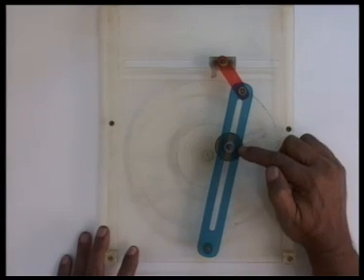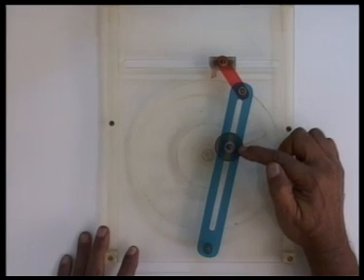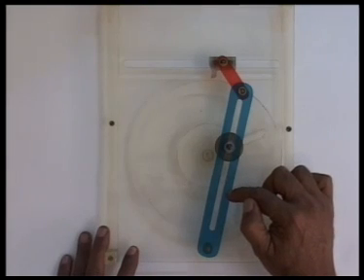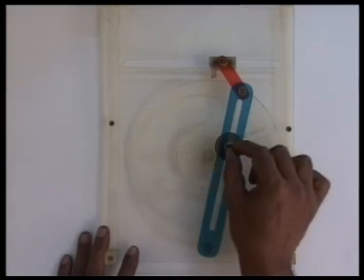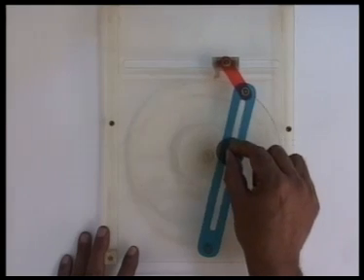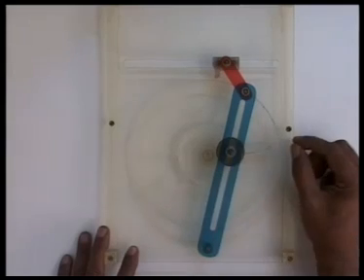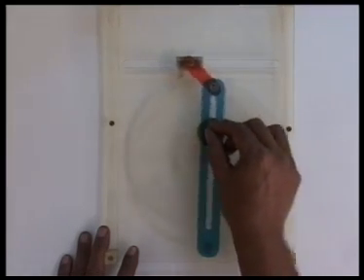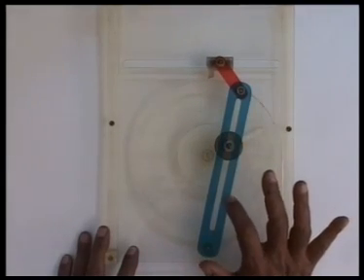But if we consider a point A4, which is instantaneously coincident with A2 and A3 at this instant, but belongs to this body 4, then A2, A3 always remain coincident, but A4 moves in a circle, but A2 and A3 is moving in a different circle. A4 is moving on a circle with this point as center. So, A2, A3 always remain coincident, but A4, A2 and A3, they have relative movement. A4 is a point belonging to this slotted lever.